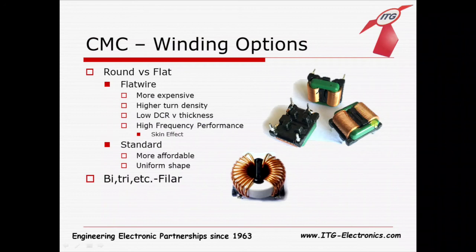Especially on an E or C core, you have a flat surface that these all can just stack up on really nicely. Whereas the round wire, you don't get that same nice stacking even on an E core. Obviously, this is on a toroid, so it's not going to be exactly one-to-one in looking at it. But as you can imagine, you're going to get a very high efficiency of winding and stacking rectangular wire versus round wire. It's the same reason boxes for shipping are some variation of a rectangular prism, whereas you're not going to see very many tubes or round boxes to ship. They don't stack nicely, so you don't get as high of a storage efficiency, space efficiency with that copper.